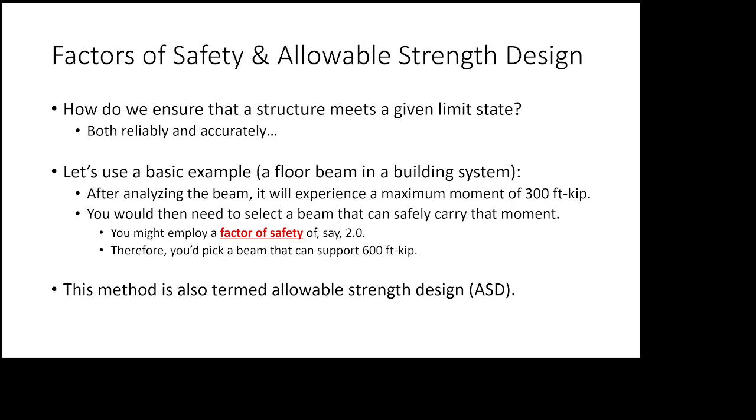And that cover distance changes depending upon whether it's a beam inside a building or a pier in Miami, right? You might use 4.5 inches of cover in Miami, but inside of a building you might use 1.5 inches because you don't have to worry about exposure to the elements inside a building like you would in the salt air near the southern end of the country. See what I'm talking about?